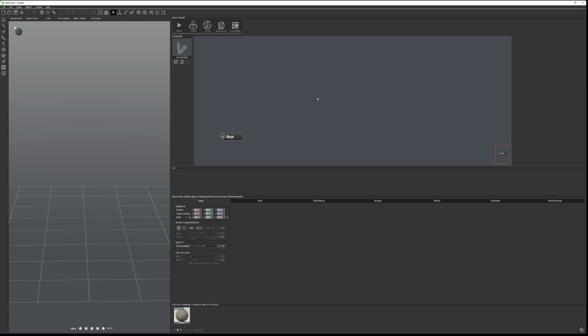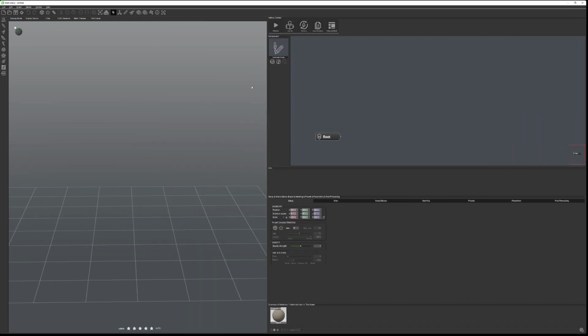So let's look right here. When you start Plant Factory, usually you have these screens, and you can see you have your isometric view and a node view. By the way, when I say node view, it means all our functionality can be created through nodes, connecting them. Like we have the root, we can connect a trunk, branches of the plant, and so on. And below we have access to the properties and some preview of materials. The properties change depending on what node we're using.